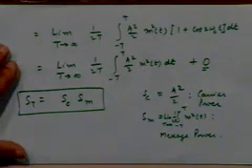So I think with this we have more or less analyzed the attributes of the modulated waveform completely. We have understood its time domain nature, what does it look like, right. We have understood its spectrum, we understood the fact that it carries more information than it needs to, and therefore occupies twice the bandwidth, and we have also looked at the amount of power that is present in such a signal. So that more or less completes our study of the DSBSC waveform.